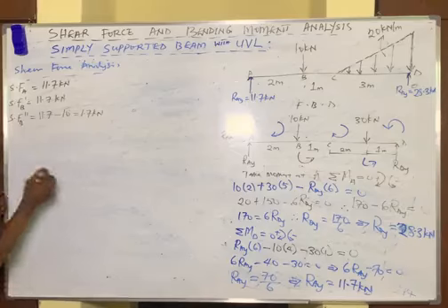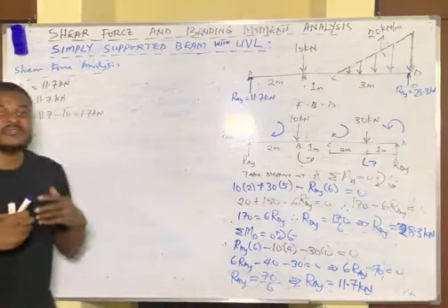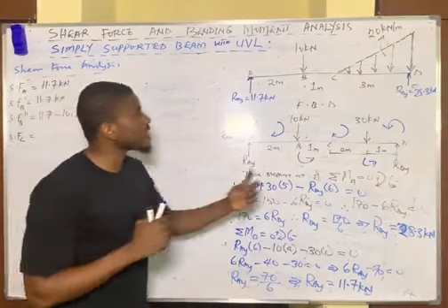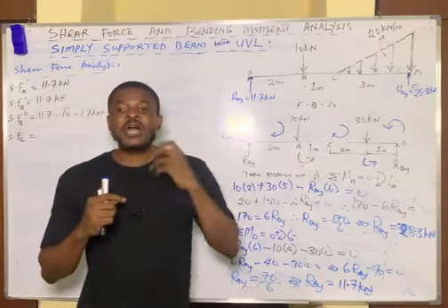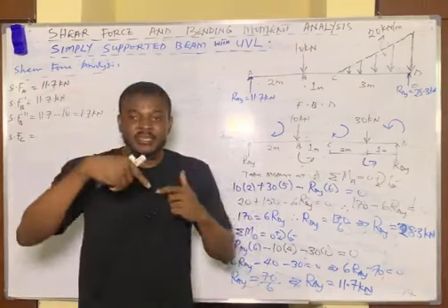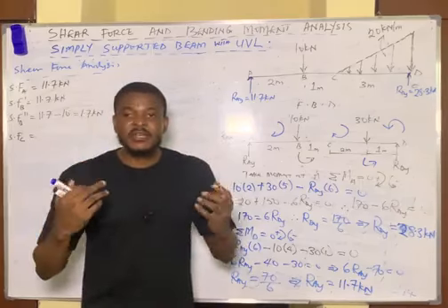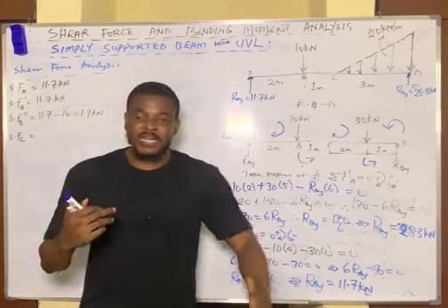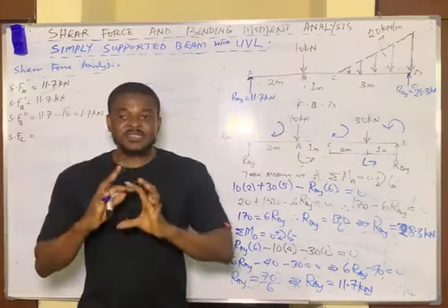So this same shear force moves now from point B down to point C. So you simply label it shear force at point C. Now, the reason why you don't say shear force C prime is simply because at point C there is actually no force. You use the prime to indicate initial if there is a force there, then you use double prime to say after, or finally, after encountering this force at this point, right? But at point C, there is no existing force.